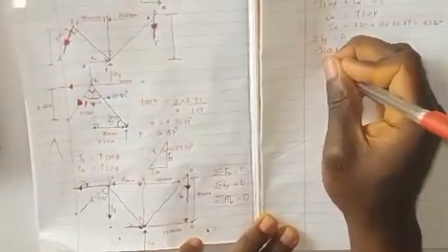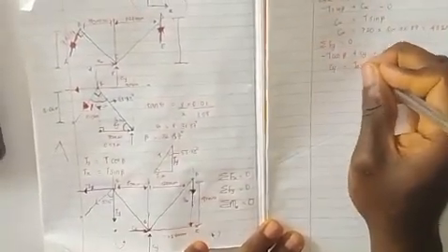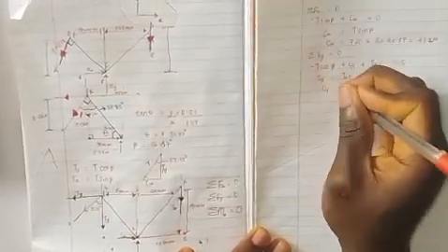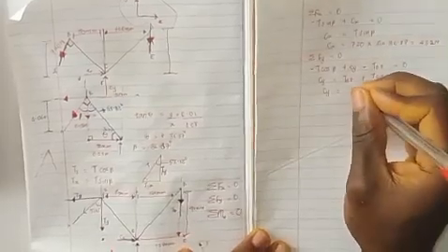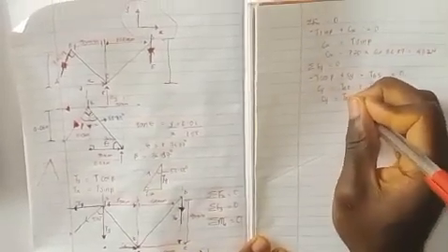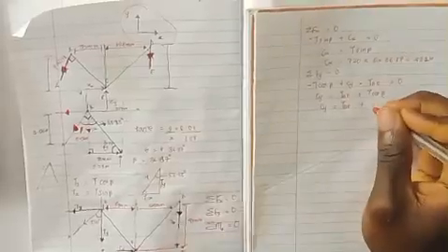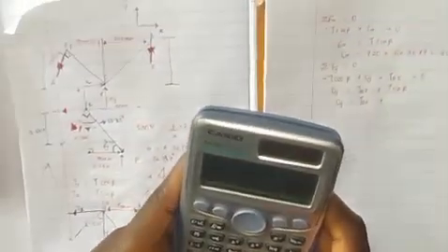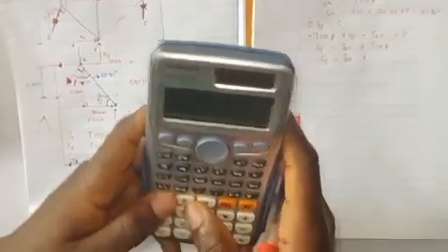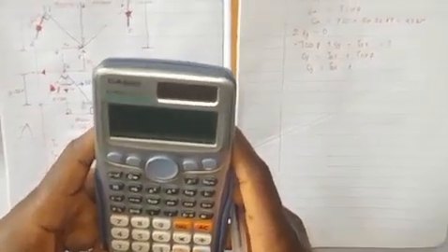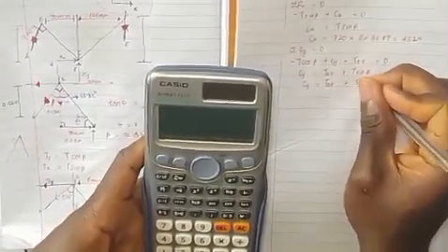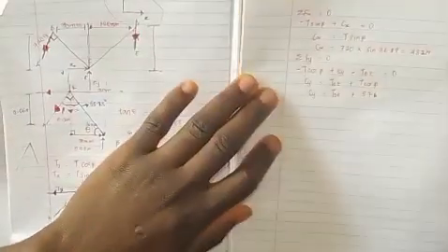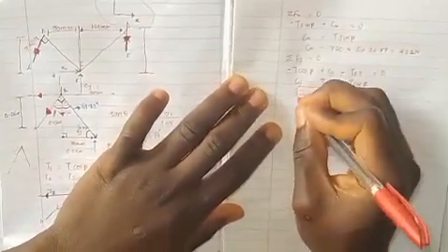So that means our Cy is equal to TDE plus T cos beta. So that means our Cy is equal to, what's our TDE? Our TDE, which is unknown, plus your T cos beta, which is 720 times cos of 36.87, which is 576 by approximation. So let's call this our first equation.